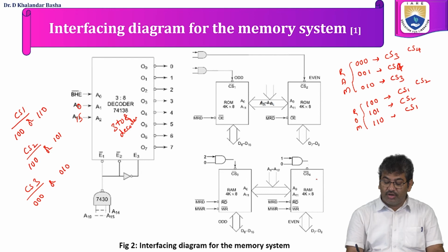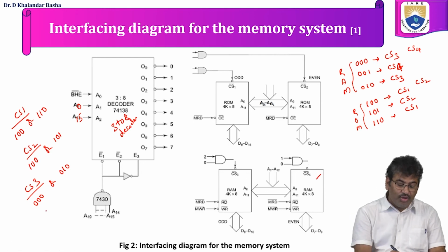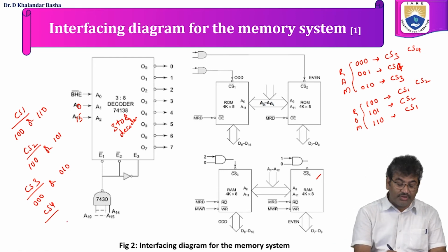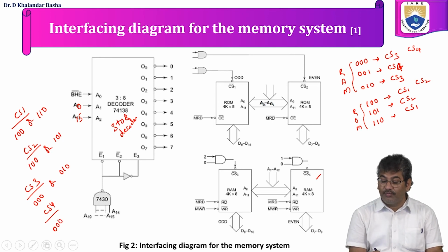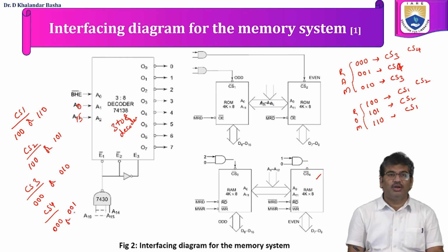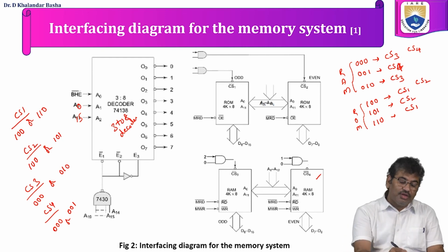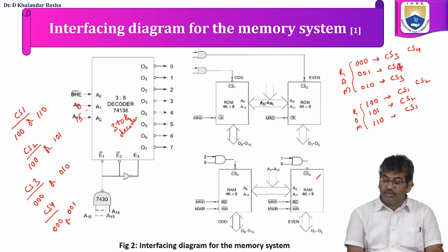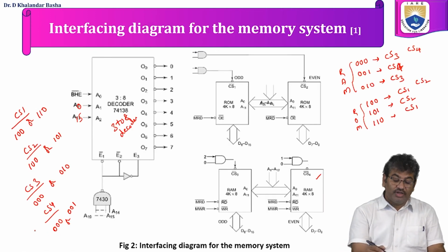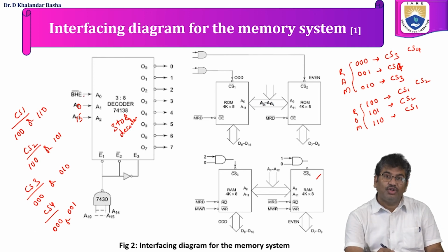The chip select 4, block 4, will be enabled whenever it is a 16-bit data transfer with respect to RAM, that is enabling the chip select 3 for the decoder input case 000 and 001. So any one of these cases, we'll go for the operation. So now for the decoder, the inputs are A15, A0, BHE bar.